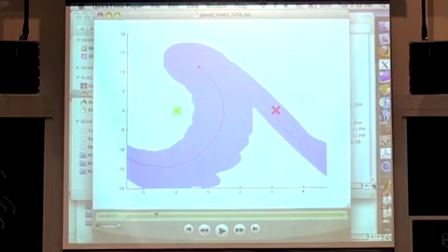If you know the basins of attraction of your existing controller, you don't have to build a very dense tree. I know if I were to pick another random point that was already inside my blue region, I'm not going to get a lot of value out of adding nodes inside that blue region. So let's pick another random point, and if it's inside the blue region, we'll throw it away. If it's outside, I'll keep it and I'll try to grow to it. Okay? So I get another random point, which is here. I'm going to pick the closest point in my current tree, which was just in this case a trajectory.